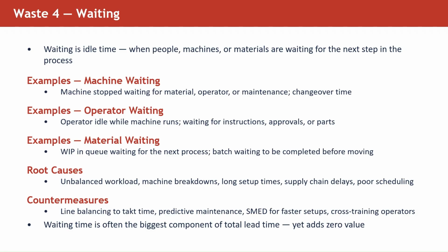Now the critical fact is that waiting is accepted as normal until you calculate its cost. Then it becomes unacceptable. Usually, if you walk through the shop floor, you'll see that a part is waiting. You think that operations are going on and the worker is doing work, but when you actually calculate the times, as we discussed earlier, from when it enters the shop floor to when it goes out of the shop floor, there you'll identify what is happening.